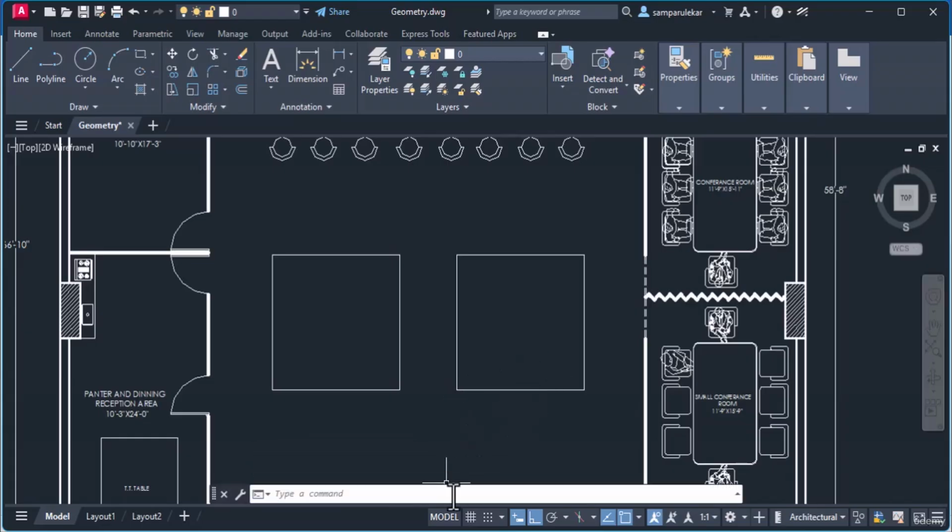Ortho is fantastic when you want to be 100% certain you aren't accidentally drawing a line at 89 or 91 degrees. So which should you use? It depends on your needs. Ortho is great for rigid perpendicular layouts. However, Polar offers more flexibility.